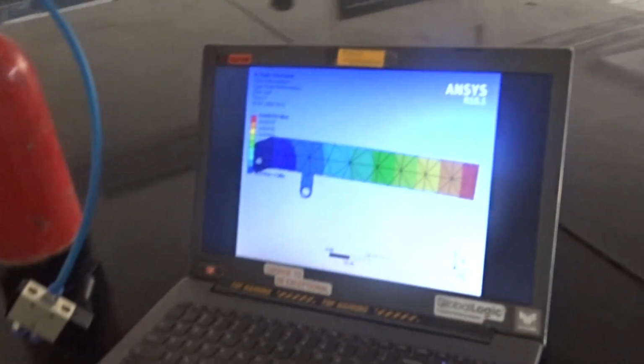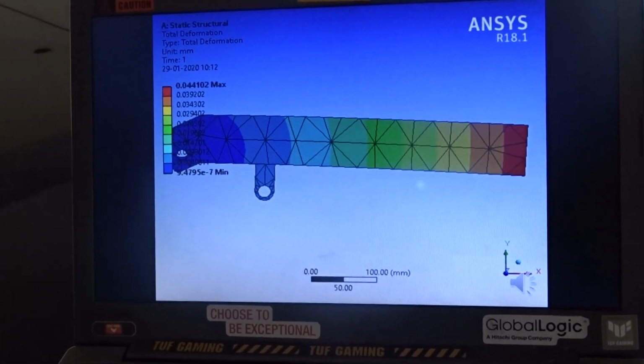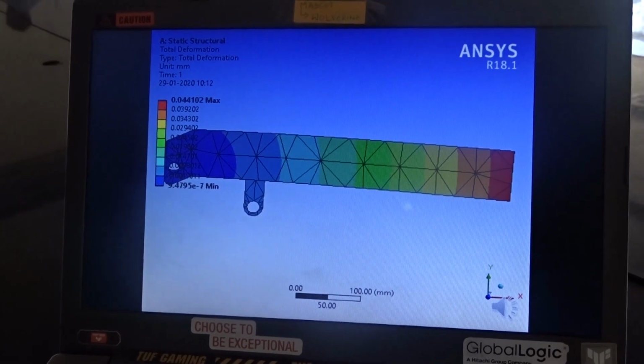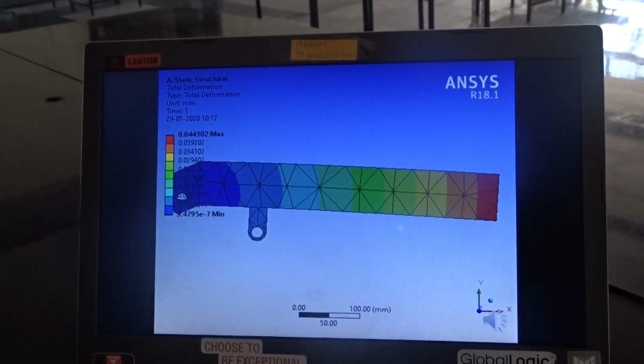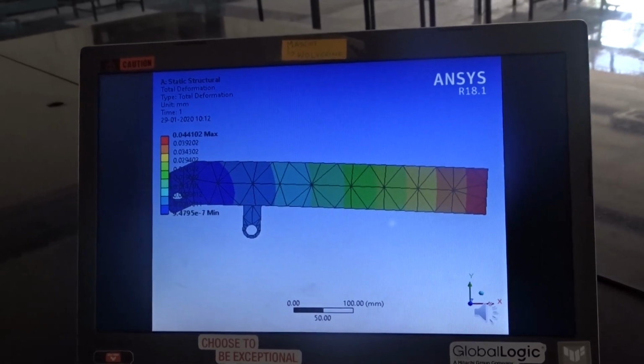And this is a very small product, which you can place anywhere possible. So the load is easily lifted and moved to any possible place. Apart from that, speaking about some USPs, I made a nodal analysis on this. Wherever the stress is maximum, I made a load division so that the stress is equally divided across the complete cantilever beam. Once the load is equally divided, the lift does not break.